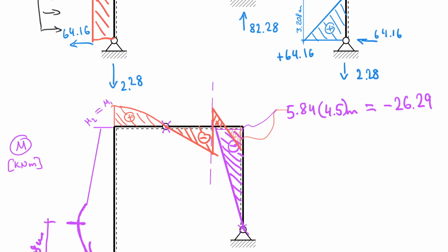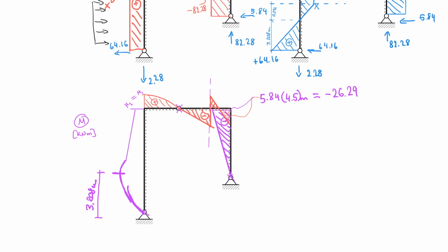Technically, my drawing doesn't show it, but technically this tangent here actually is tangent to the curve at that point. But the last thing for us to do is calculate the maximum moment and the value here, because it's also the value here. And I guess we also need to calculate those values, which I believe we already did effectively, like I said. So from here, the slope up, so minus 26.28 plus that slope here. So let's get started on that.